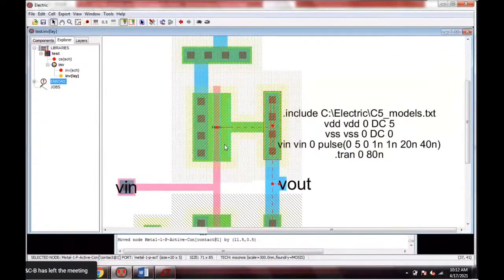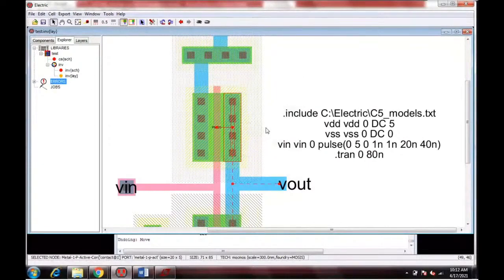In this tool I'm talking about. Whereas in Cadence it becomes connected. In this tool it is not connected unless you connect it manually like this. Did you look at what is shown here? Understood? You have to make this connection physically, and then move it so that it is placed nearby with the minimum DRC rule. Any doubt other than that?